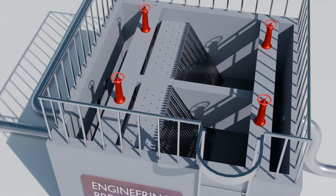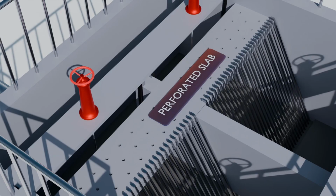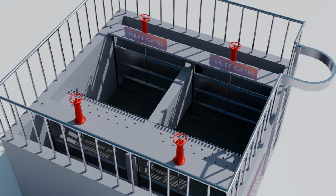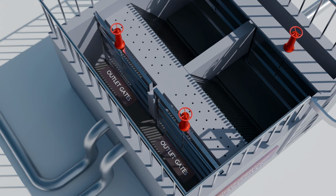Each channel is equipped with its own set of screens to capture debris. A perforated slab is also provided to facilitate safe access for operators and drain water from collected debris. Inlet gates for each channel are provided, typically with motorized controls, to regulate incoming flow during operation or isolation. Outlet gates for each channel are also installed to control outgoing flow during normal operation or maintenance.